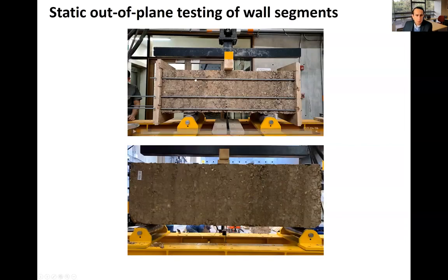Also, we have done some kind of beams. These are actually out-of-plane walls that we install horizontally to see the out-of-plane behavior. Without reinforcements like the wall here, we need to reduce the span of the specimen so we are able to actually see the failure, because otherwise with the self-weight it will fail without any additional weight.